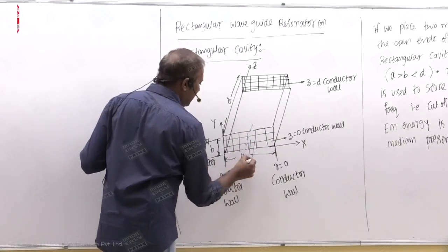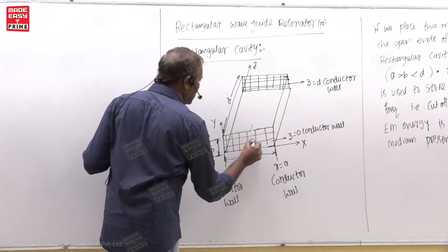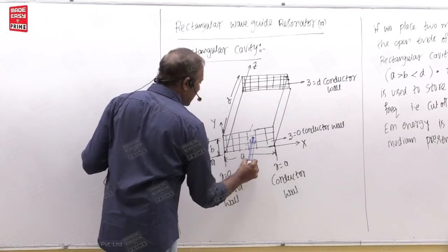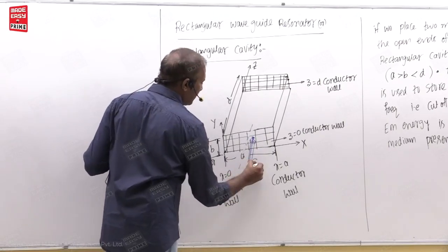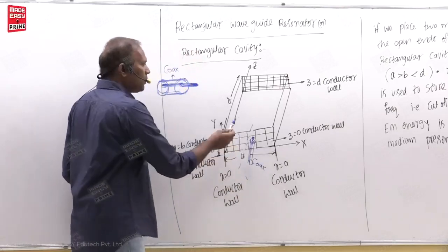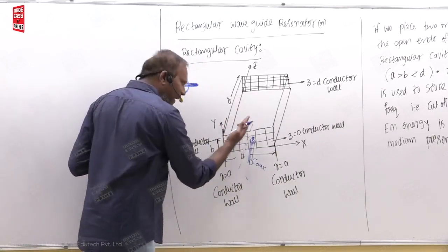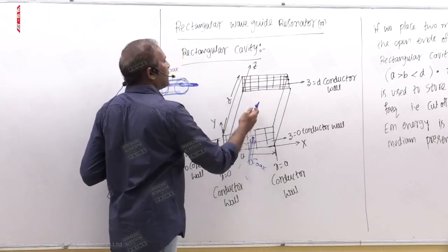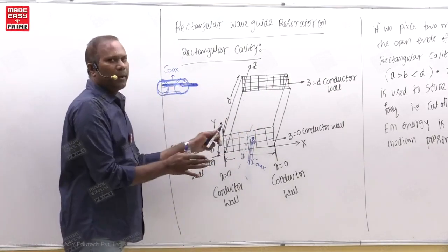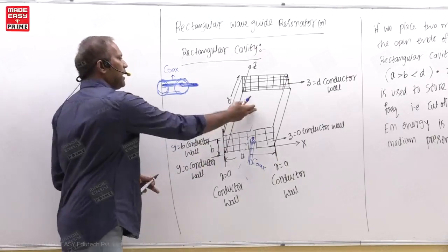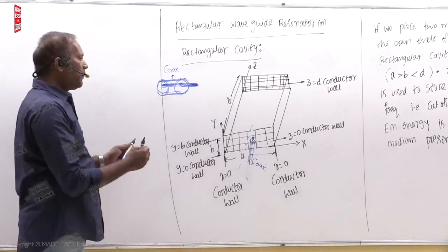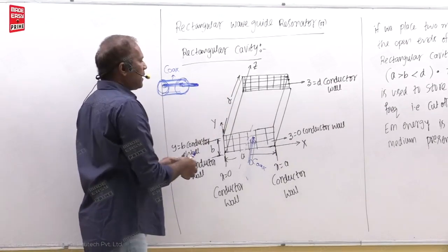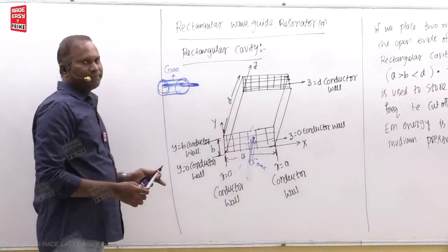That coaxial cable sends energy into this, the probe, the inner conductor. So when you want to store the energy, first of all you have to send the energy. At the beginning, if you send the energy, it travels in Z direction, and once the cavity is filled up, it stops receiving the energy. So at the beginning, the EM wave travels in the longer dimension, the D is bigger actually here.